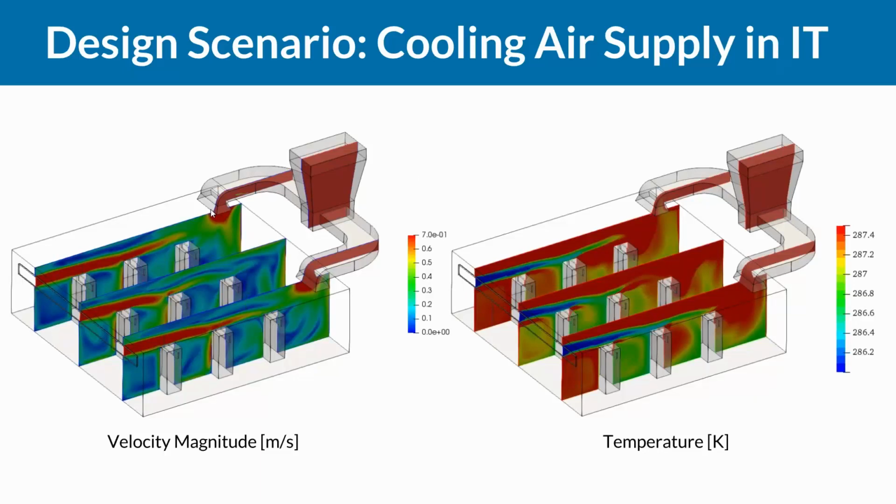As you can see here, we can use slices to see the effect of what's happening. The flow is coming here, then this cold flow, the blue one, will hit the first computer, and we will have a recirculation region here. That's why the computers behind the first one are really hot, and this is the main reason, because we are stopping the flow in front. But actually, if we didn't run this simulation, we were not able to understand what is going on.